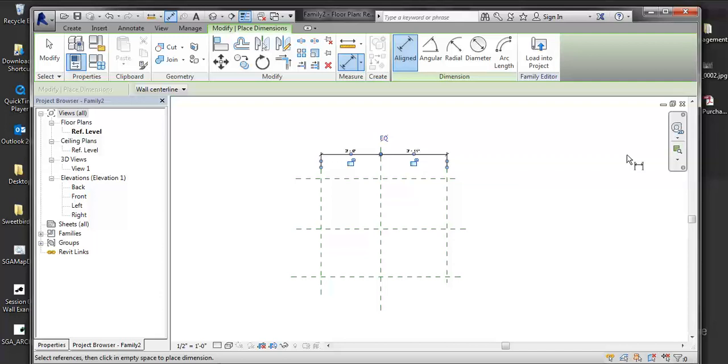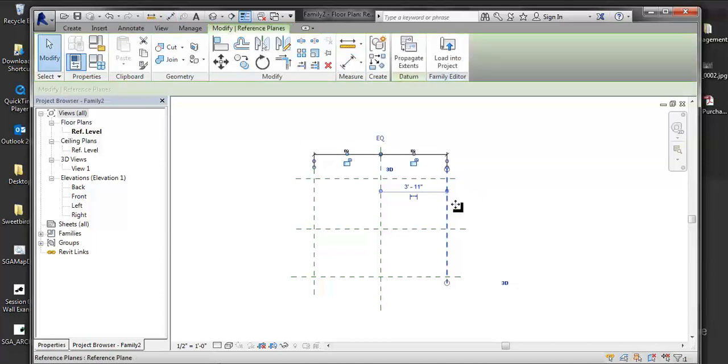And if I pause and hold, there's three things that we need to talk about. If I lock this, I lose variability in my system. If I click on EQ, which is an equality constraint, let's go ahead and do that. So I'll click on EQ. It's going to immediately make those two items equal. And if I escape twice out of there, now when I pull one side, it's going to flex, what I call flexing the model. It's going to flex the other side.